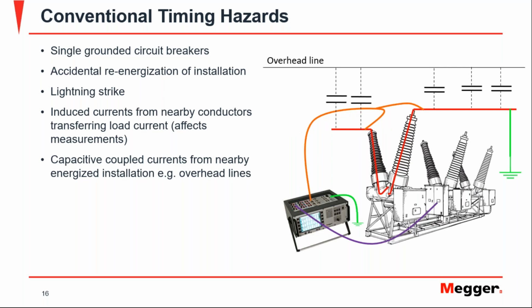Sometimes we are under pressure because of the time constraints that we have nowadays with equipment being out of service for testing. So you've completed the test, everything went fine. Now everybody starts disconnecting things, and if the ground is not in place, and somebody disconnects these leads, not first from the instrument, then all of this induction is now going to be at the end of that cable, and you can see burns, or equipment damaged because of that disconnection.